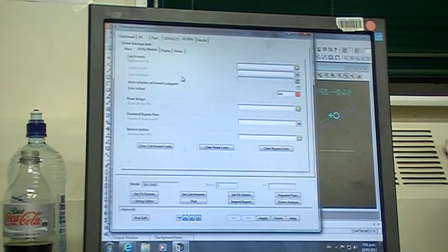Okay, with label models, the type of textile that we have, overland bypass flows, I don't think we will have time to get into that for this course. Basically, this is what happens if a manhole blocks completely, how much water is getting into it. If it can't all get into that manhole, where does it run to? Can that next manhole take it? Can that next cesspit take it? We can do all that, so you're working out how much can fit under the ground, and then if it ends up in overland flow, what do we do with it? Okay, I'll see how we go for time as to how far we push into that.